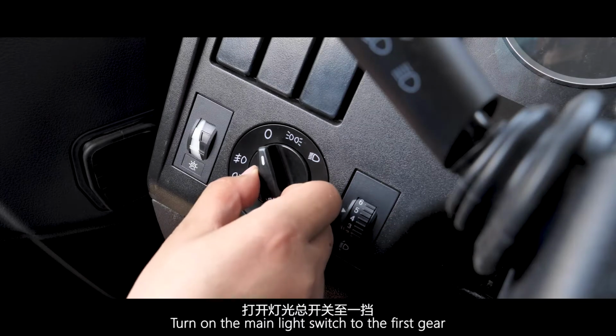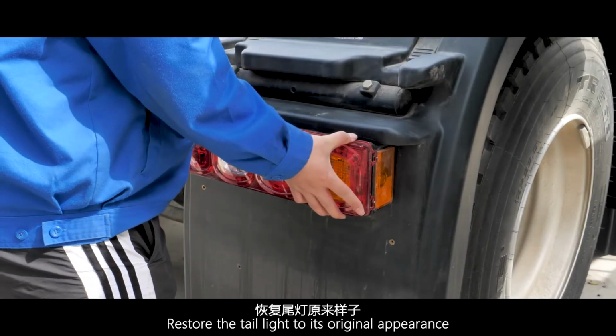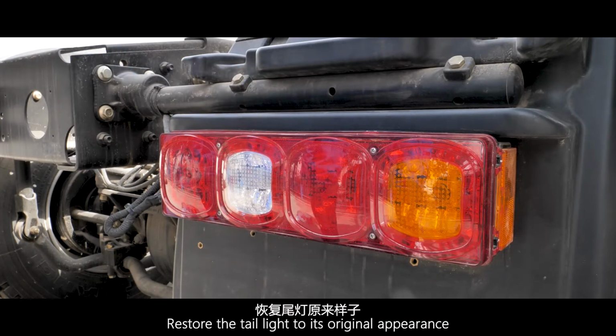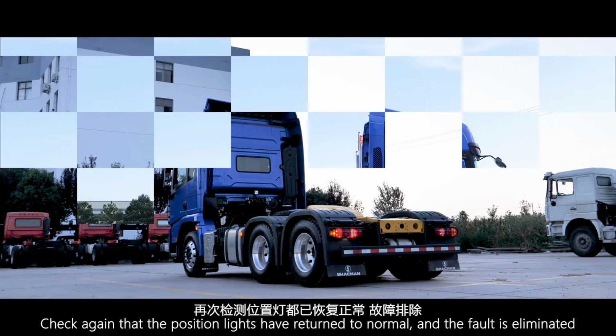Turn on the main light switch to the first gear. The right position lamp returns to normal. Restore the tail light to its original appearance. Check again that the position lights have returned to normal and the fault is eliminated.